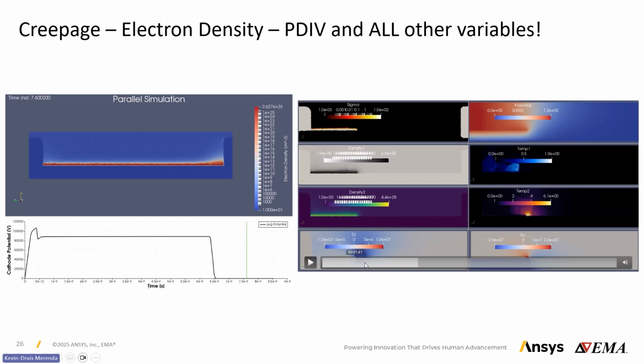You can see ESV here. This is the field value that I'm talking about that increases over time as the gap effectively gets smaller and smaller as the discharge gets to the other side. And then sigma is the conductivity of the medium that we're tracking. So we're able to see the conductivity of that discharge changing through time. And the fields Z here are very high, effectively keeping also the track along the surface of the dielectric.